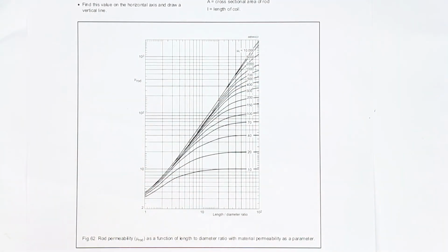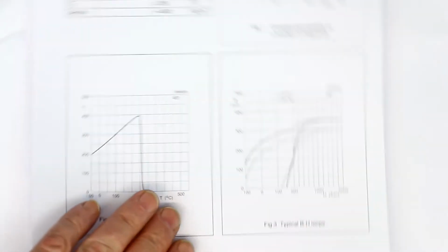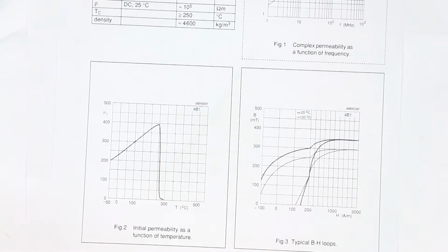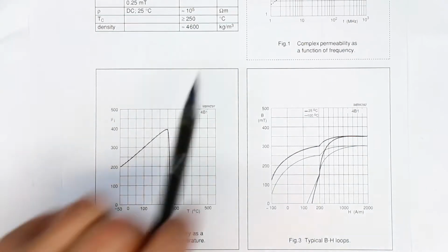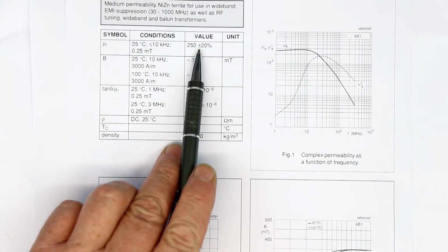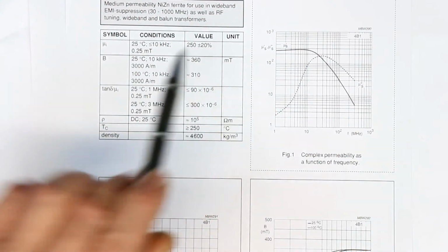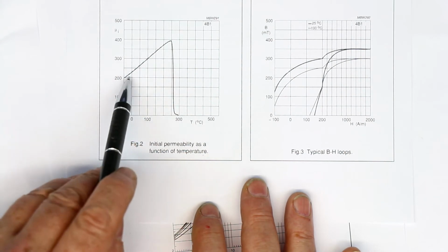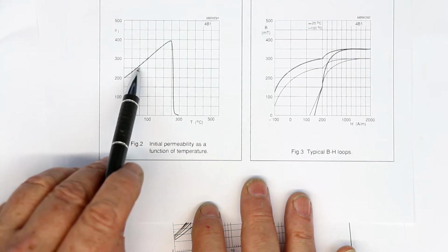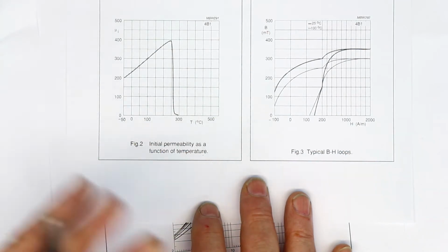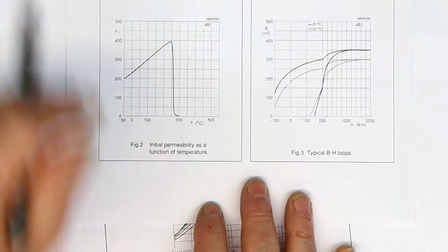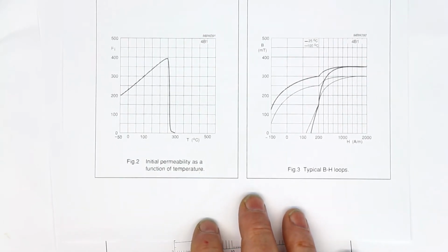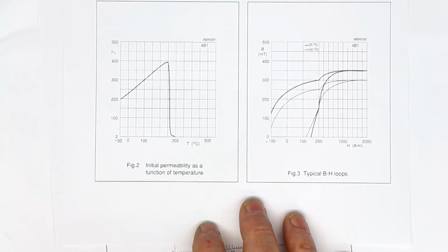And there is a third factor, or even more than a third factor: the permeability, which is essential in calculating the coil, has plus minus 20%. Well, that's okay, we can deal with that. But it's also temperature dependent, quite largely. And the last factor, what we basically want to gain with our spreadsheet, is the Q factor.